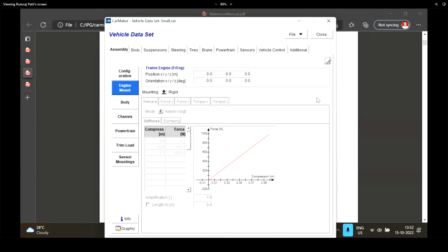The entire calculations in the software will be done based on the reference frames, so it is of paramount importance that those reference frames be entered as accurately as possible. If you have created a complete vehicle model in your CAD package, you can create multiple coordinate frames in that and correlate the same values with your CAD package. In this way, you can minimize the time to completely parameterize the car, even if you have used some different reference frame.